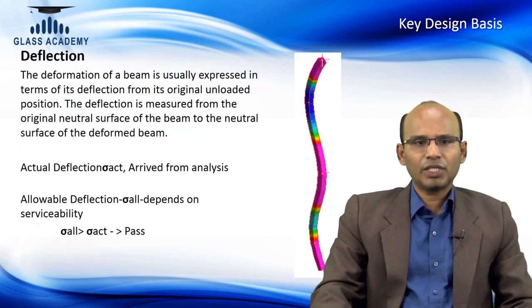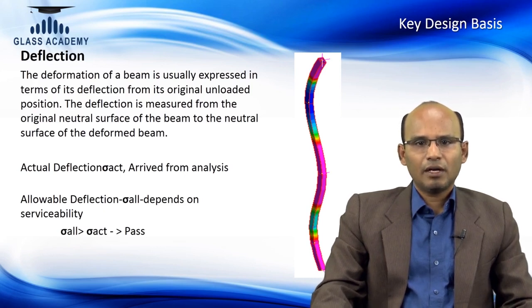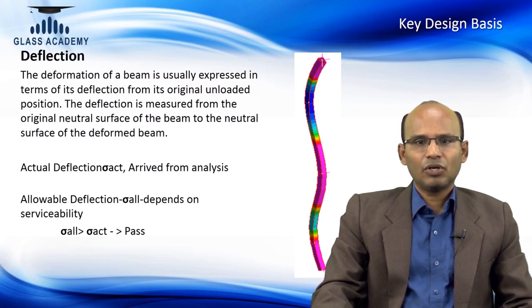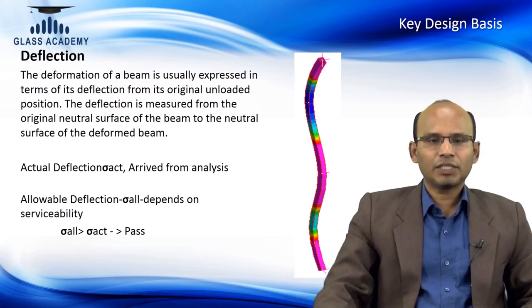We have been so far checking for strength. Here we are checking for deflection. A deflection check is critical to make sure the member is deflecting as the engineers are assuming, and this is going to be deflecting for wind loads, or sometimes for live load. So, the members, glass and glass elements need to be checked for these different criteria. It is primarily driven by the wind loads, could be negative wind load or positive wind load.